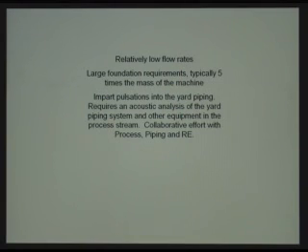So, like we said, relatively low flow. Oh, the other thing about recips is that they impart pulsations into the yard piping because the compression is not continuous. It's a reciprocating operation. As the piston pushes the gas, it compresses the gas up to the discharge pressure, and then it suddenly pushes it out into the yard piping. That causes a pulsation, which can cause vibration inside the yard piping. And so to be able to avoid that, we need to do what's known as an acoustic analysis.